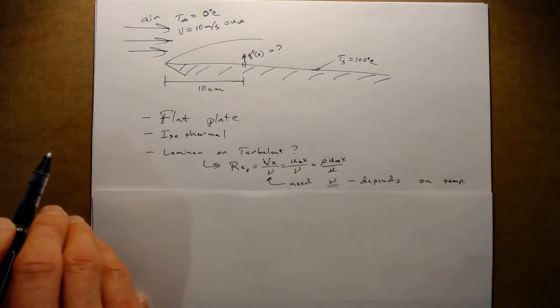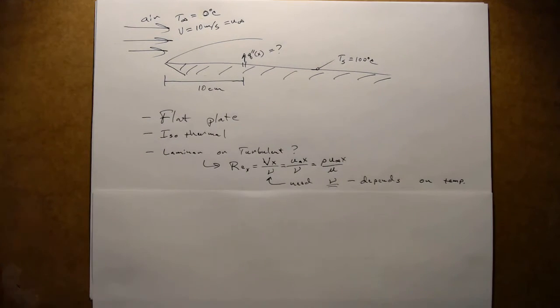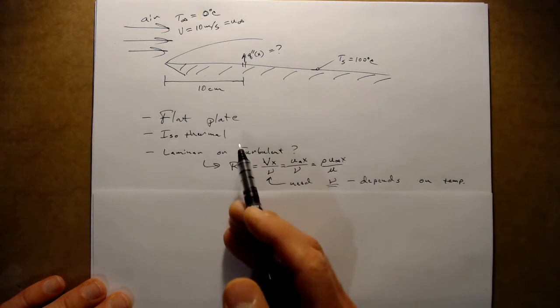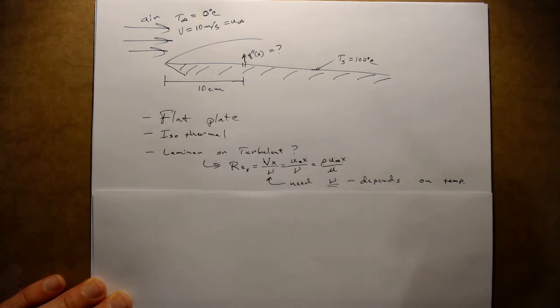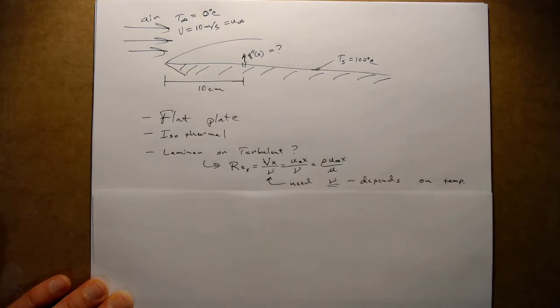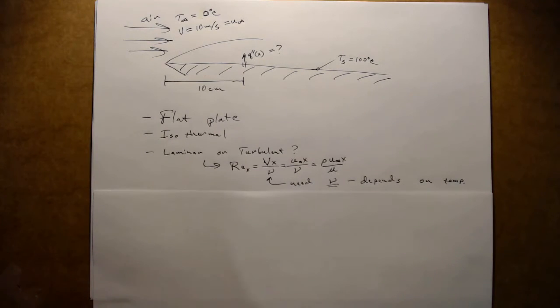And that depends for certain fluids very strongly on temperature. Actually, it turns out for air it's not so sensitive. But for example, at room temperature, it could still double over a range of, for example, 150 degrees C. If I went from 300 Kelvin to 450 Kelvin, my kinematic viscosity would almost be 2 times as large. We can find for liquids, almost invariably, well, at least most commonly, liquids' kinematic viscosity decreases with temperature, and those decreases can be extremely large, orders of magnitude.